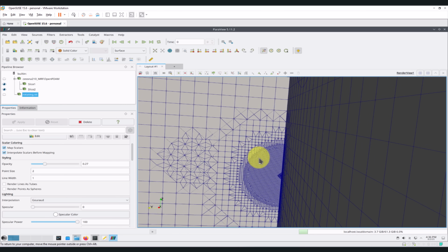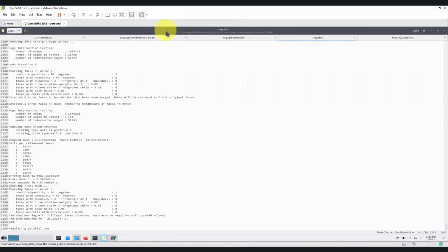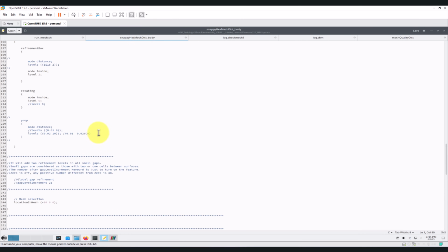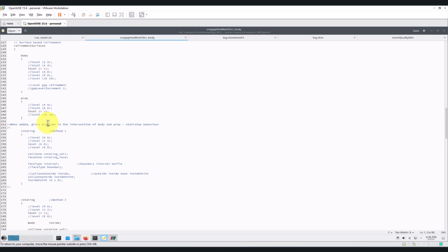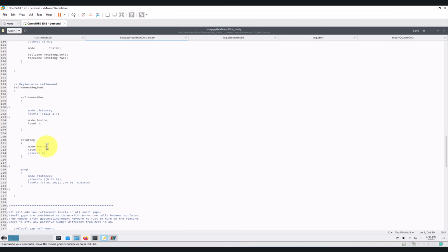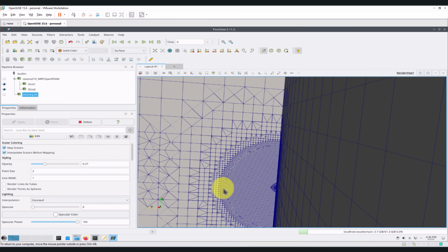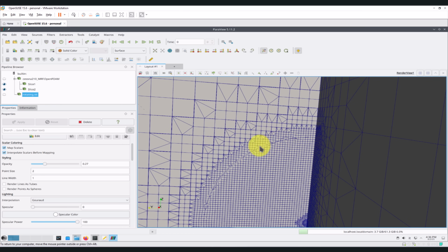Yes, you use finer meshes, and yes, you take that surface, for instance, you go back here, and in this rotating refinement region, actually you go to refinement surfaces, and not surfaces, this will be a surface on top of a surface, and you can add another like this one, a distance mode, okay, on the cylinder, a finer cylinder. It can improve, but still sometimes you are going to have these issues here, okay?